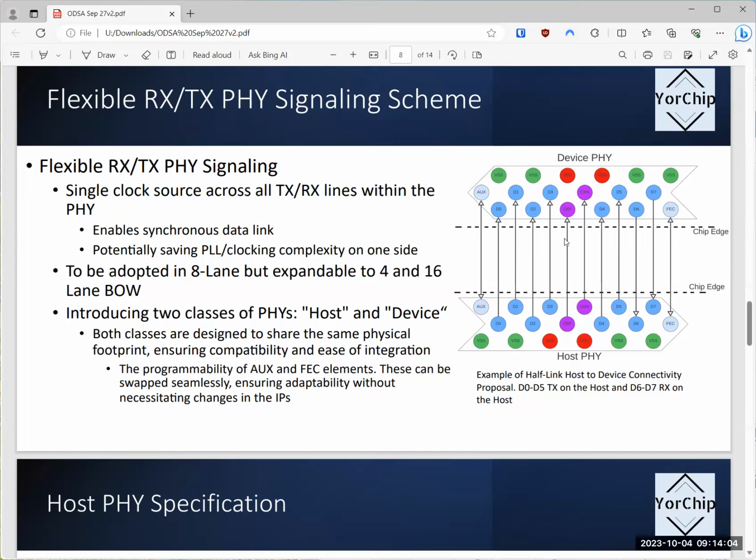Yeah, no, that is true. I think what you're saying is absolutely correct. There are a couple of questions, though. If you wanted interoperability with some other PHY that was not built this way, then you would really need both the TX and the RX slices. I mention it because in case you do need that, you're stuck paying for it in any case.